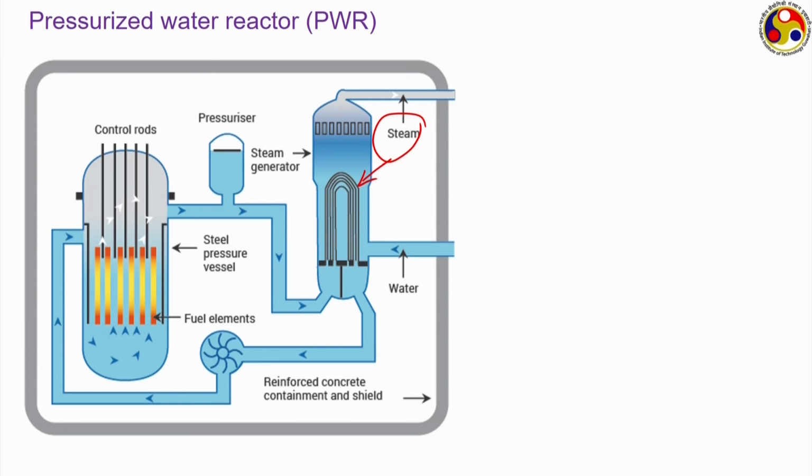So, the moderator and the coolant and also the water in the outside circuit are all water from a chemical point of view, but the water which is used as the moderator inside the reactor is not the working medium. Rather, the working medium will be water, but some other body of water, or some separate quantity of water, which circulates only in the external circuit.